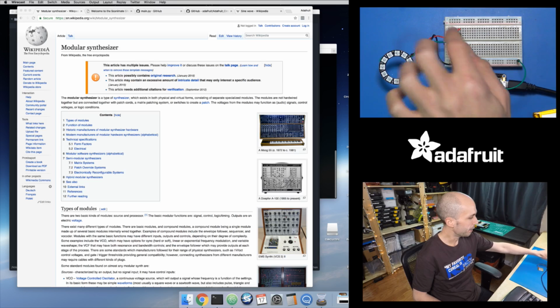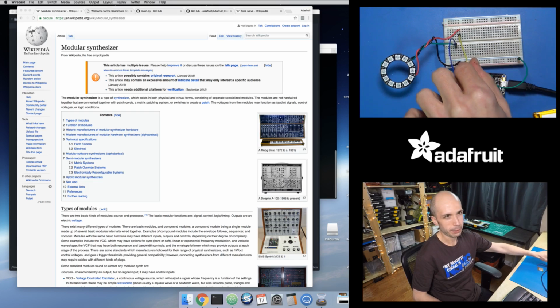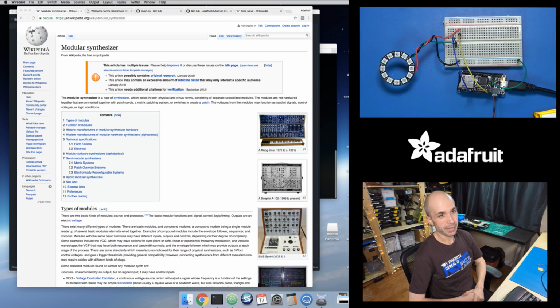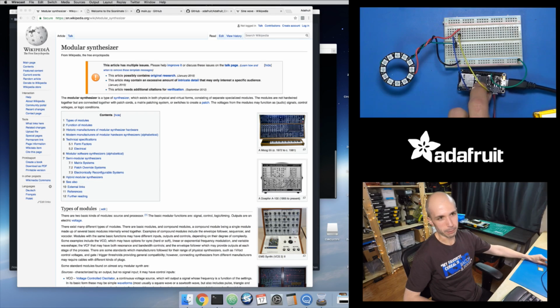And then the red wire is the power line for the NeoPixels. Now the power does get kind of tricky with NeoPixels. If you're driving a lot of NeoPixels, they can pull a lot of current. Each pixel alone can pull 60 milliamps of current. You multiply that across 100 pixels, you're pulling 6 amps sometimes. I mean, that's maybe not 6 amps, but 600 milliamps. That's almost an amp of current for that many pixels. So that's a lot of current to pull. So you don't want to pull that from a power regulator on your development board.